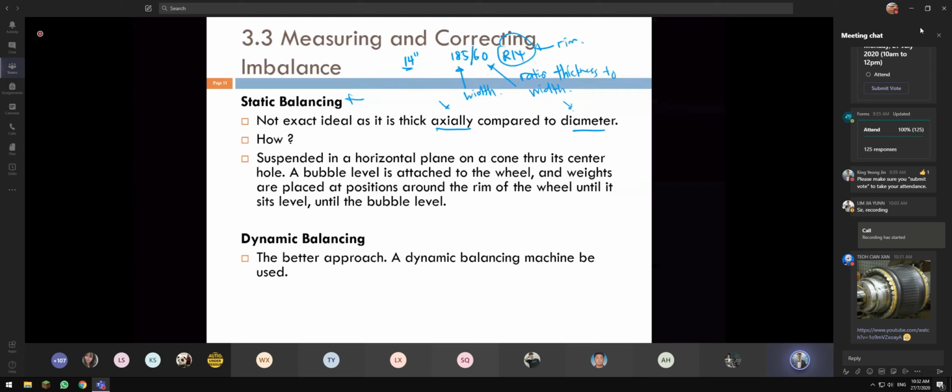That's why when we say low profile tires, we always look at these numbers. Low profile tires may be at 40 or even down to 30, right? And so on. If you want a wider tire, you choose a bigger number here, but you always have to make sure it fits the rim.